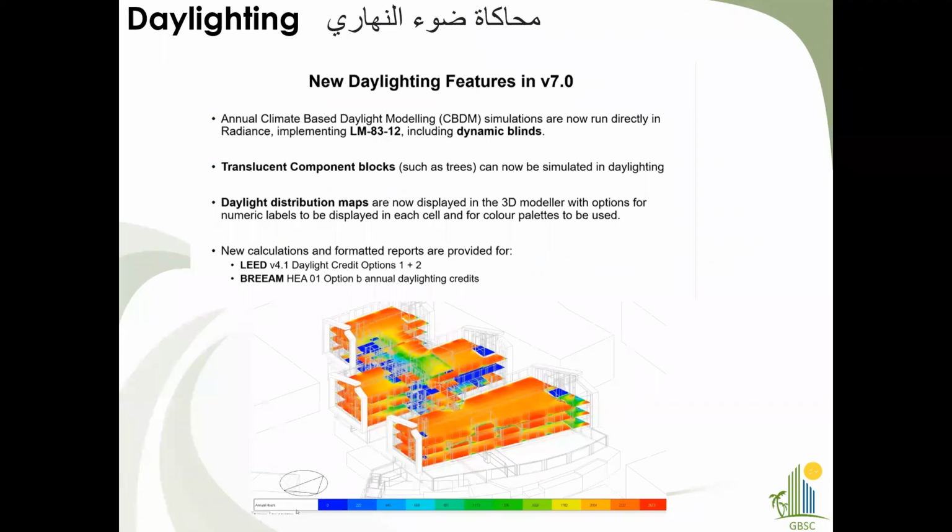For daylighting, within DesignBuilder we can perform point in time daylight analysis and annual daylight analysis. We also have integration with LEED version 4, LEED version 4.1, and LEED version 3. All those LEED modules are inbuilt and integrated within DesignBuilder, and we can even generate reports from DesignBuilder as well. Apart from that, we can generate 3D outputs for our 3D model, so we can see what kind of spatial distribution of daylighting there is within the zones, in the corridors, or any kind of space that we have designed.